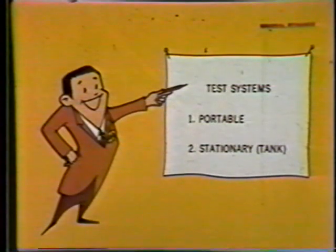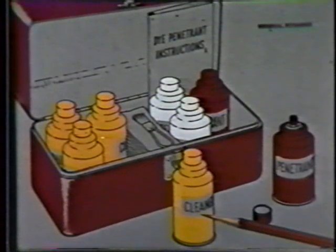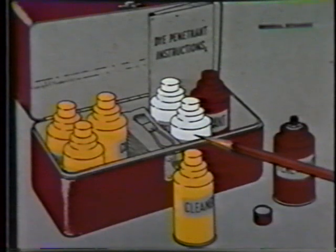There are two basic types of penetrant test equipment, the portable kit and the stationary or tank system. This is a visible dye kit. It consists of a carrying case, solvent cleaner or remover, red dye penetrant, and a non-aqueous wet developer. The kit includes wiping cloths, a brush, and operating instructions. Materials are easy to apply, and they produce high contrast indications in visible light.